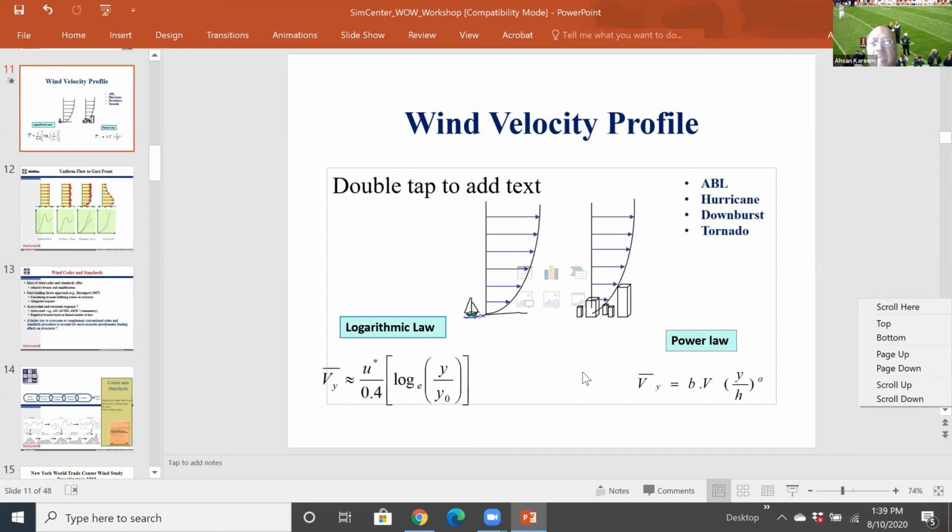Yes, because if you are just looking at very tall buildings, like the ones you are seeing in New York City now, or for bridges, this is cables. This is highly desirable to have this capability. But I think this area of a little cladding piece getting pulled out, then it will sort of flutter around the building. That is a local fluid-structure interaction problem, which is essential also because that is the one which would enhance the stresses in the components and eventually the peel off. So hopefully that response satisfies that question.